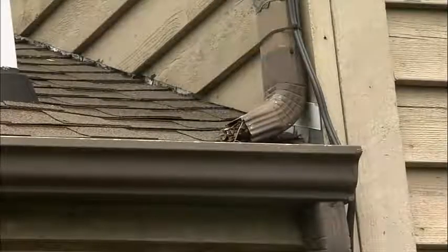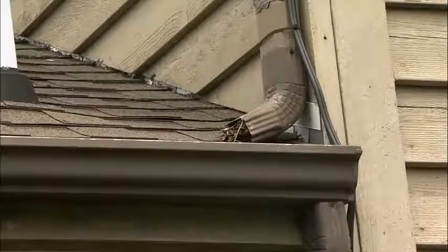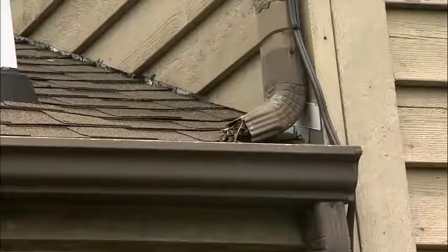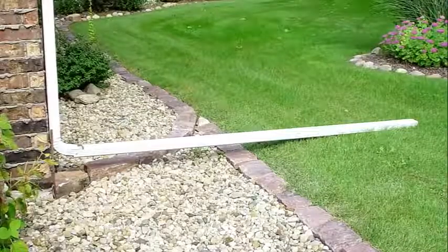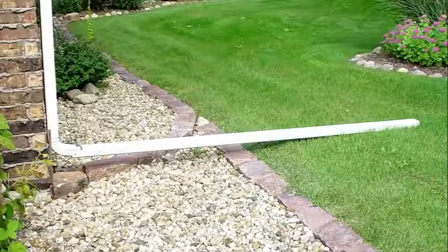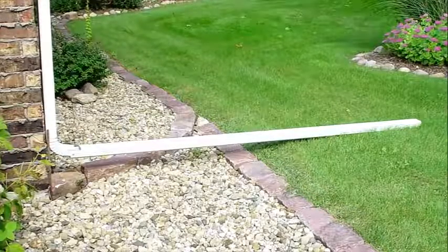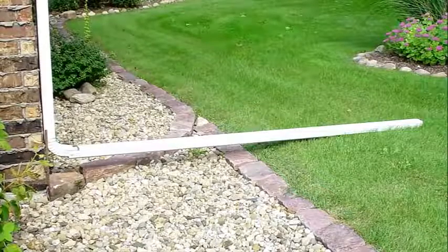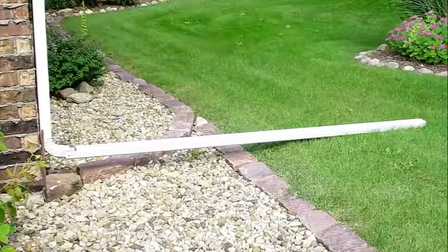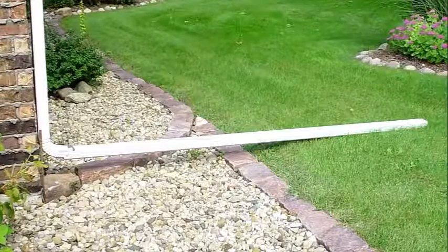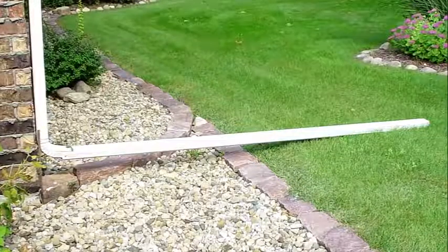Even an average amount of rainfall can cause problems if the home's roof drainage system is inadequately sized and poorly maintained. Downspout laterals should be sized and maintained to properly discharge several feet away from the foundation of the home. 10 feet is recommended by some home safety groups. Care should be taken not to discharge too close to the property line, as it may cause water problems for the neighbors.